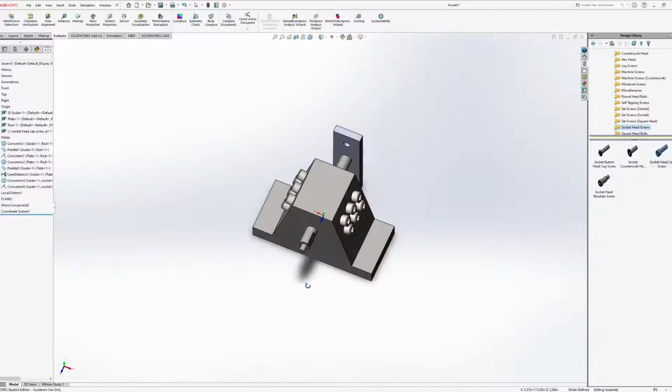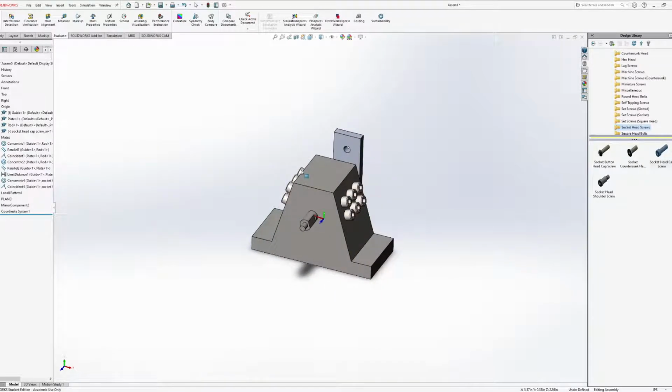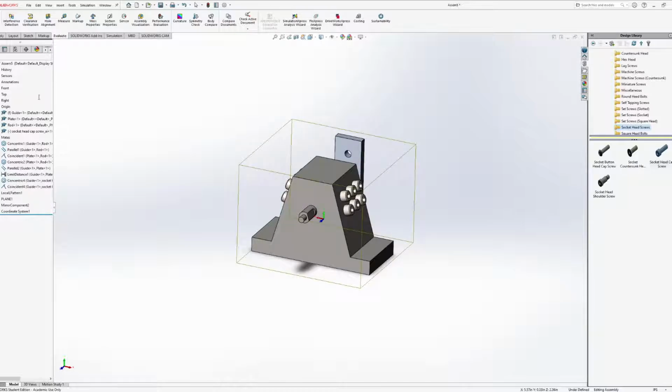Based upon where our global coordinates are, the x center of mass is 3.32, the y is 1.55, and the z is 3.32. Now, what if we use our other coordinate system? Well, it's going to change. Not by much, but it did change a little bit. We can see now that it's 2.25, 1.22, and negative 1.04. So all of these things have some sort of impact on how the geometry is.